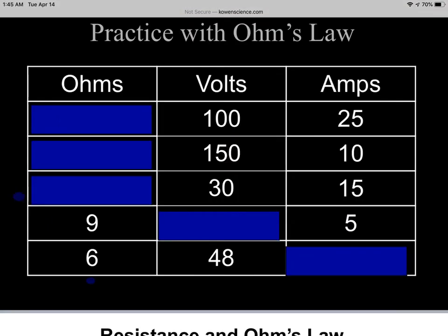Here you have some practice problems if you'd like to try to do these. I do want to mention one problem. It's problem number 7 on your homework, and it says, what is the increase of current when 15 volts is applied to a 10,000 ohm resistor, which is adjusted to a 1,000 ohm value? For finding the increased current, I solved for current with the 10,000 ohms: 15 volts divided by 10,000 ohms, and I got my current.